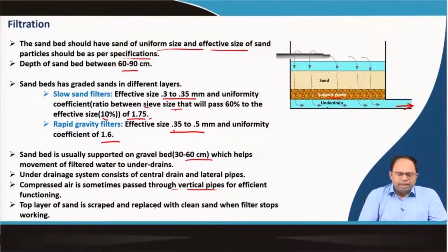Whenever we see that the filter is not working, that means a top layer has formed which is preventing entry of water, which has gone thick. So, we have to remove the top layer of sand, clean it, and put it back again.